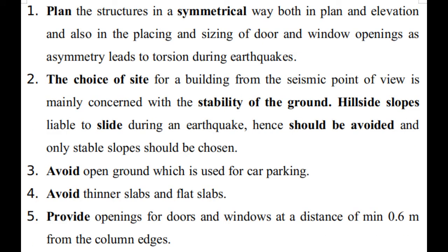Let us look at the different points or different aspects in the planning. Number one, plan the structure in a symmetrical way both in plan and elevation. And also the doors and the window openings should be placed, and their size should also be symmetrical, because if it is asymmetry, it leads to the torsion during the earthquake.